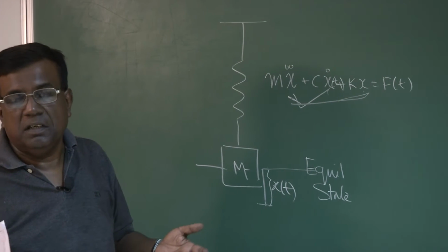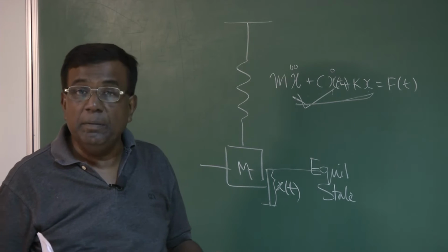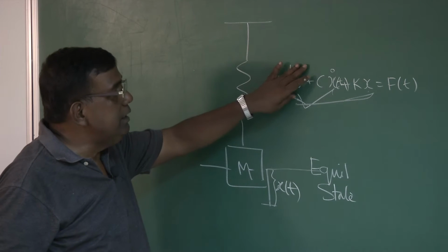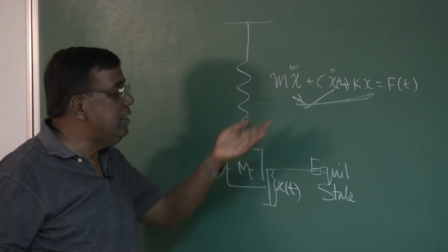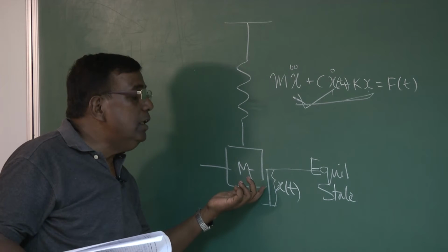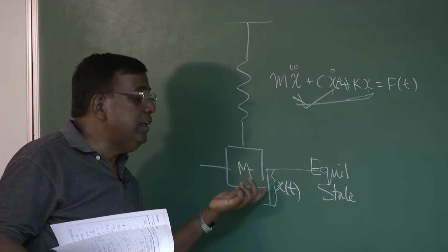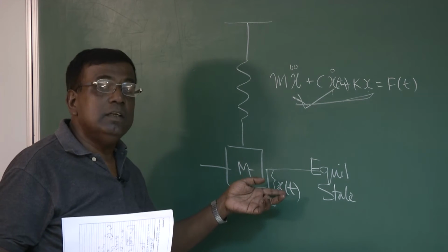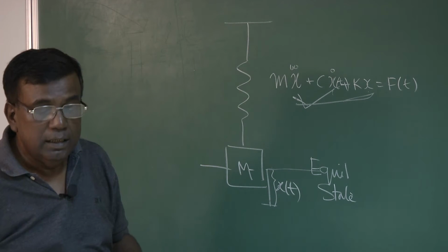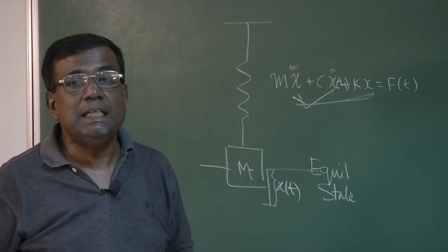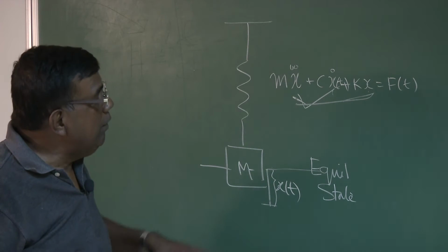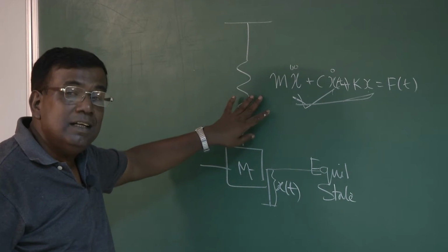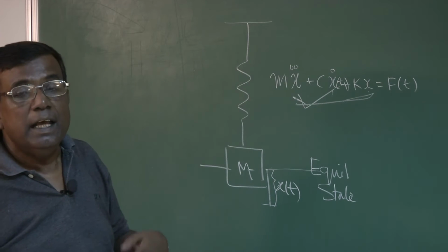So, we said it corresponds to either an oscillatory return in the underdamped case, or the overdamped case, or the critically damped case. But the catch was that this x of t is measured with respect to the equilibrium. Another way of understanding is: if I disturb it and withdraw it, I see how this motion variable, which is a perturbed quantity, is behaving, and based on that we say whether it is dynamically stable or not. Now, we wanted to extend this understanding to analyzing aircraft dynamic stability.